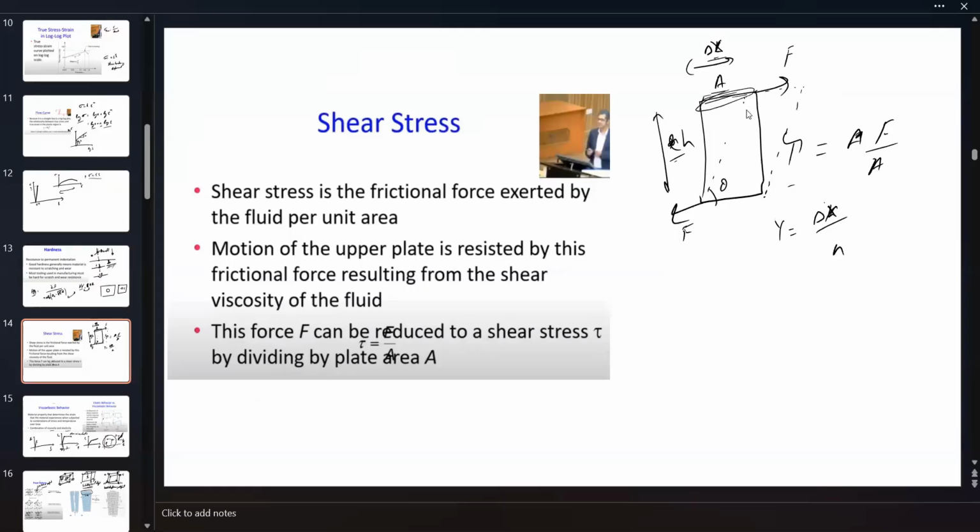Then you have shear stress. Tensile or compressive stress is applied along the same direction. In tension, both ends are pulled apart, and in compression, these two ends are compacted together. However, in shear stress, force is applied on the surfaces parallel to them.